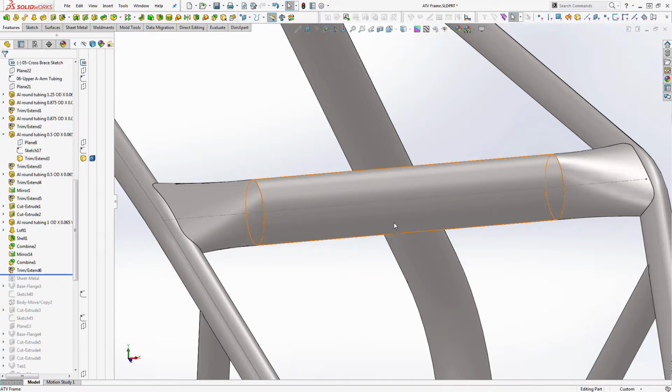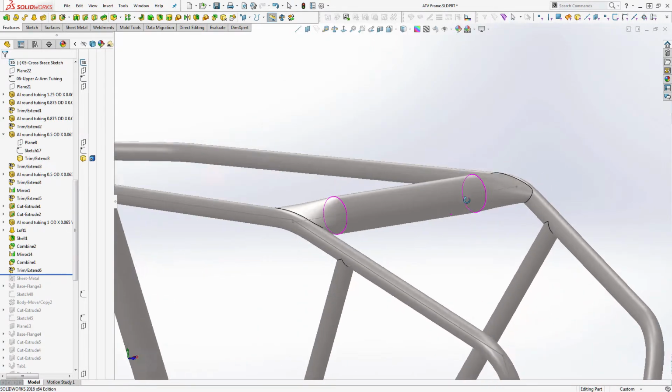So once you got to a certain look, you'd want to be able to reproduce your crush, and you'd want to be able to reproduce your trim with your tubing notcher. So this would take some time. This would be a lot of hand work and getting some things set up that once you got them set up, you wouldn't want them to change. So I don't know how feasible this is in real life.